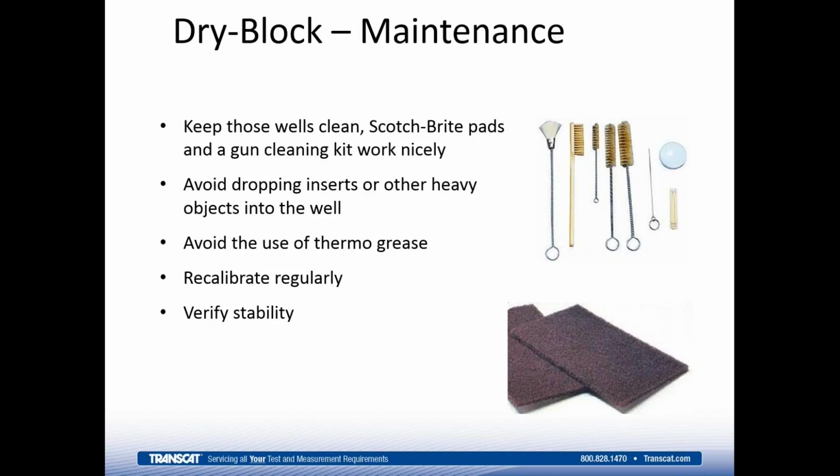The dry block inserts are made of metal. When metals are used at high temperatures, they oxidize, and the oxidation builds up over time. One option to clean these off is a Scotch-Brite pad, but it's hard to get a Scotch-Brite pad down inside of the well. So we typically use a gun cleaning kit here. That sort of thing will work nicely for a periodic maintenance point where you go through and clean it out, and it'll continue to work well for you for years.